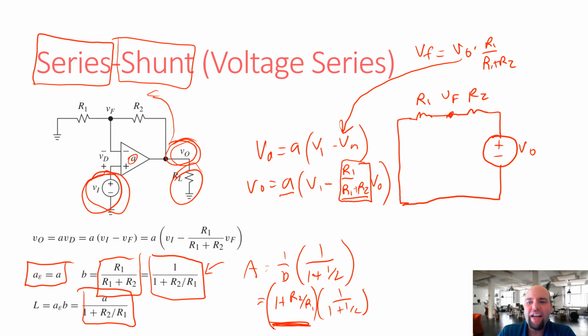And you might say, why then? Why did we go through all of this? Because when we analyze this system as a feedback network, this is already given to us, right? I was able to pull this equation out of last lecture. I didn't need to resolve this. I didn't need to solve for, oh, what's the impact if alpha is 10 to the 4th instead of 10 to the 6th? I already know all that. All I had to do was find A epsilon and B, and now all of my equations for all of those non-ideal cases are already known. We established them last lecture. Now we can just plug in the values once we find them.